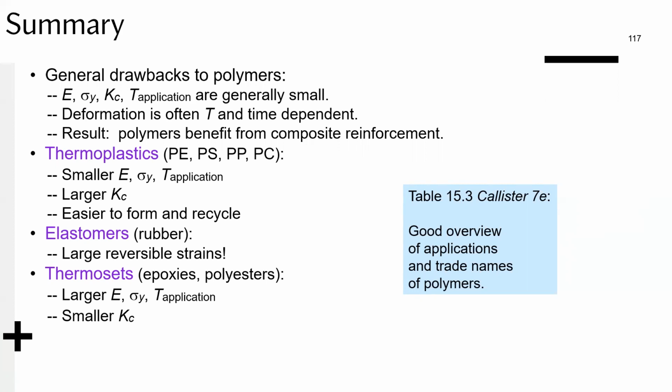So what they really do these days with polymers is they typically reinforce them with other materials. So you can have a mesh and then use your polymer as a filler. So you always have a backbone that acts as the stiffening, where the rigidity basically comes from that. And then you have the polymer that gives it the elongation and deformability that it requires.